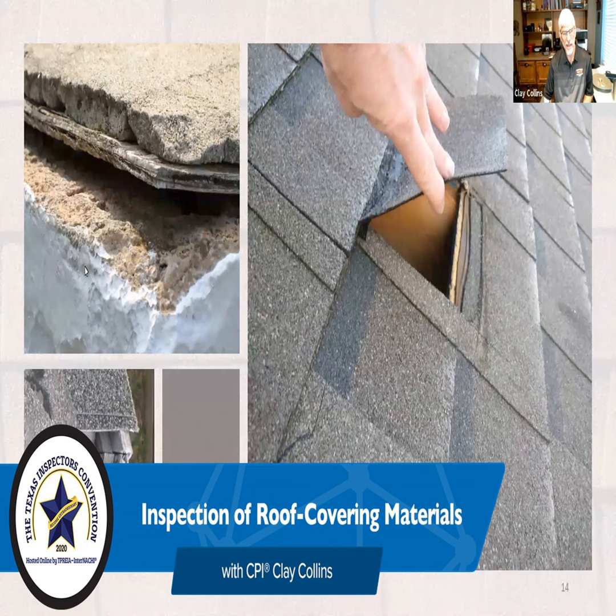We're required to report evidence of water penetration. Well, we can see that in the decking, the ceiling. We can see some in the walls. Usually it's going to be the ceiling before we see it actually running down the walls. We might see it in windows and floors. And seeing it on floors might be unusual. It'd have to come all the way down the wall and run under the floor covering, or just on top of the floor covering. But we're going to see that on floors occasionally.